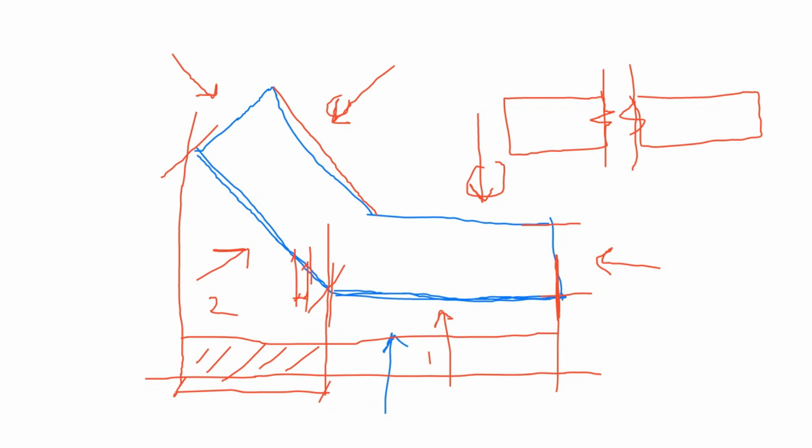The other comment that I just told you about is that if you do have, for instance, landscape in front of your building here, maybe approaches and trees like this in here, and you project it and look at it from here, you would see trees like this and a tree like this. This is not a construction working drawing. You have to unhide those or remove those in order to reveal the building, because the concept here is not to show the building aesthetically, how the tree is interacting with the building. The concept is to show exactly how your building will look. So this is regarding your elevations.